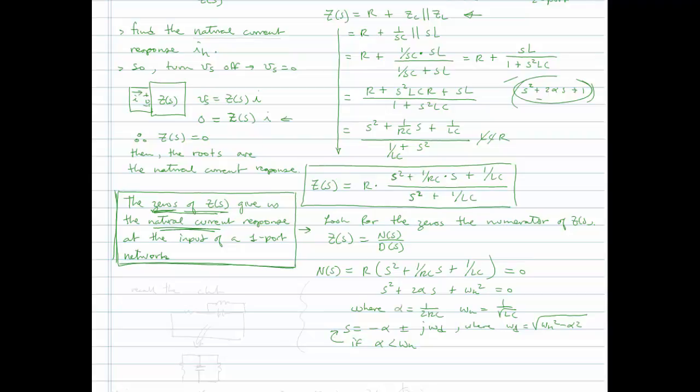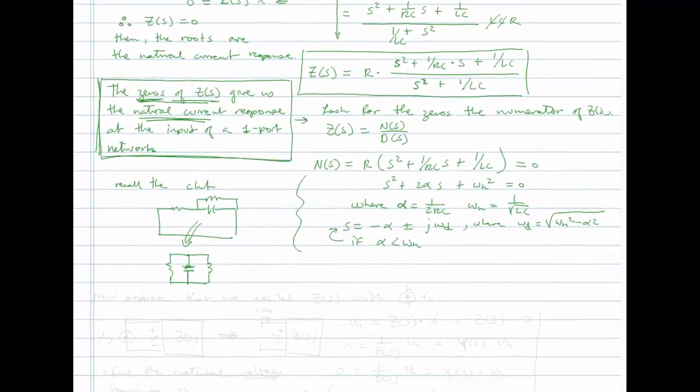It's just the method by which we actually arrived at this. Now look at the circuit. Let's consider the circuit. Alright, the circuit is simply this. R, capacitor and inductor in parallel, and now we're going to short the input. Right? This whole thing is just simply a parallel RLC circuit. Alright, and you've written the differential equation on the last homework and found the natural response, I think, for it. You certainly calculated alpha to be 1 over 2RC. And here we have it. But we never had to write a differential equation. We actually did it by using impedance.